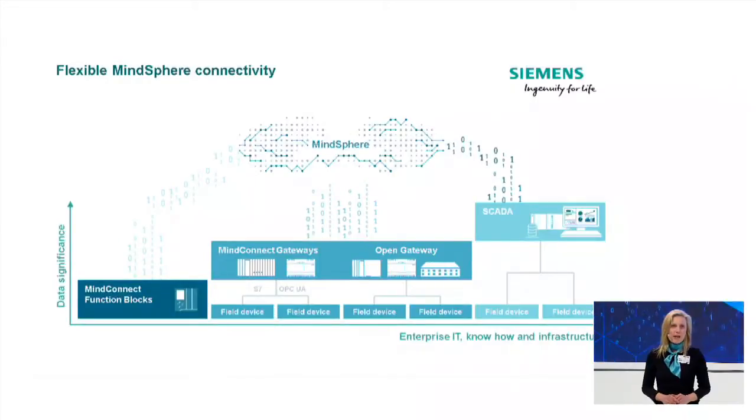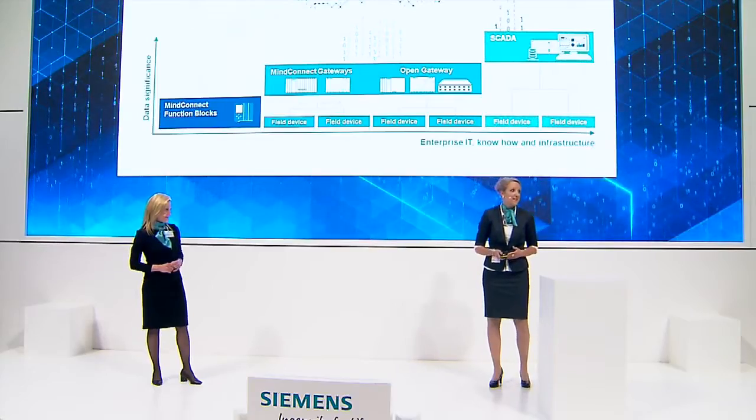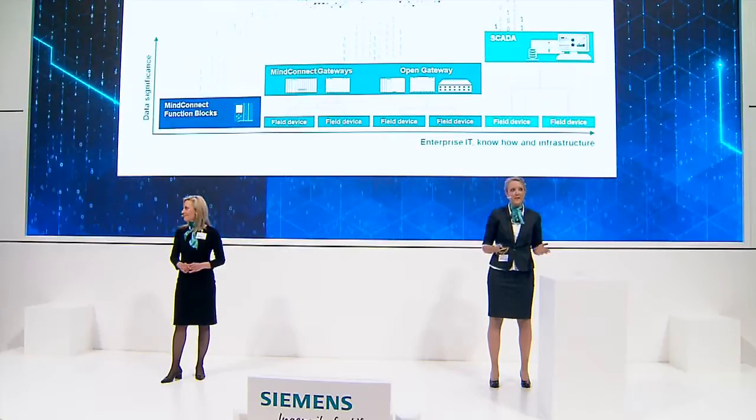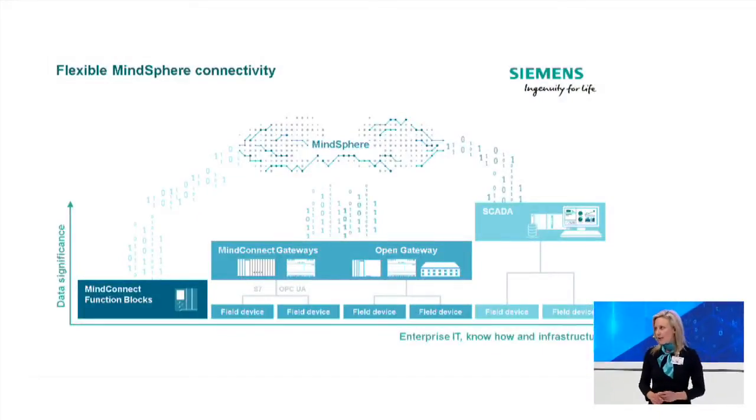To connect to the MindSphere, you can choose from 3 possibilities. The first possibility is to use directly integrated functionality within our S7-1500 PLC using MindConnect function blocks. The second possibility is to use gateway or network connectivity, such as MindConnect Nano or MindConnect IoT 2040.